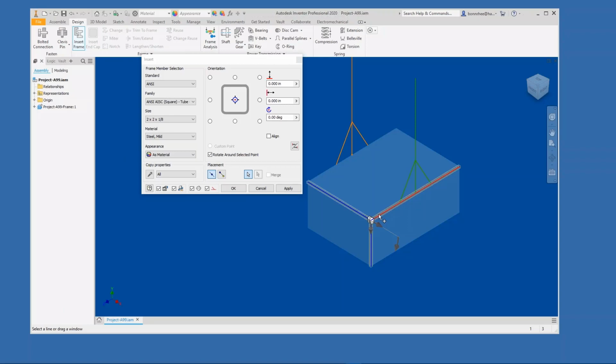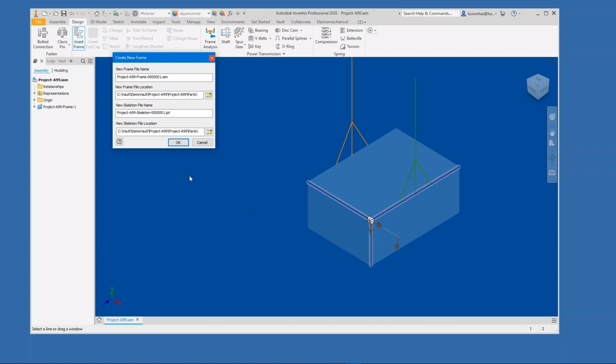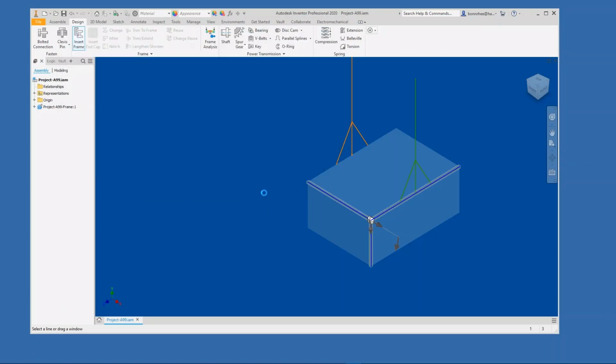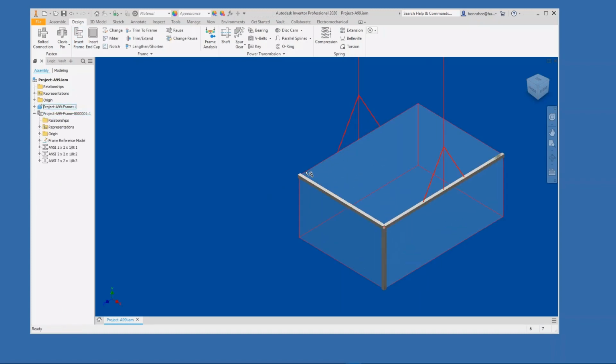In my mind, where I came from, this part we'd like to reuse the same part number, right? So in actuality, this part is the same as this one, and this one, those four, and then these shorter parts are the same as this one, and this vertical part are the same as these four. So all I'm going to do is place those three. I'm going to say okay. We'll leave the part numbering the way it was. Now, instead of placing all those, I only have 3 parts.